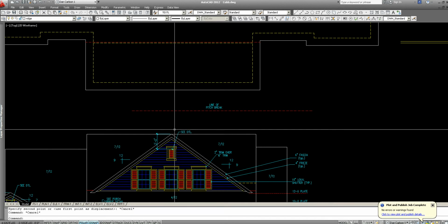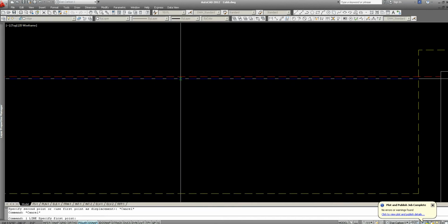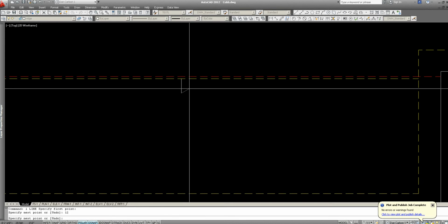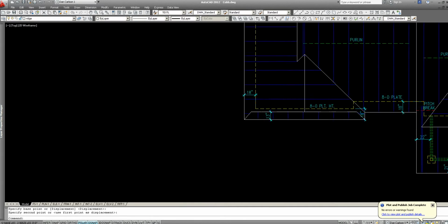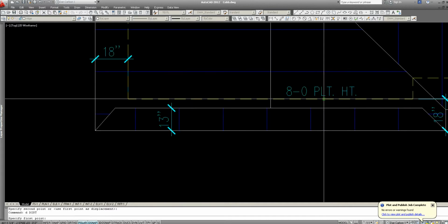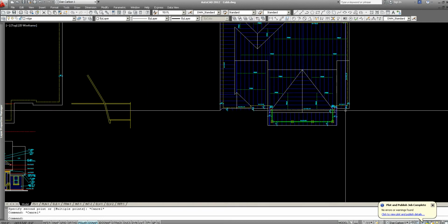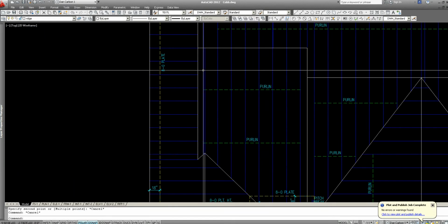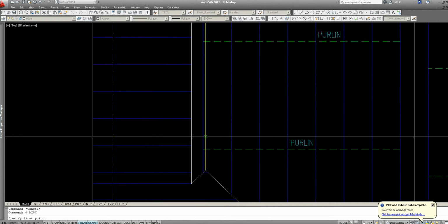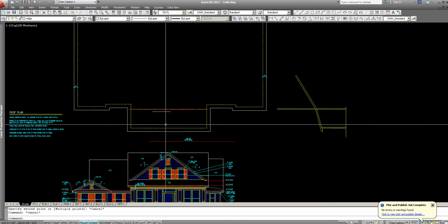So then we know that our gable end, let's do a 12-inch overhang because I think 12 inches is more appropriate for gable ends. In fact, if we look over here, we can see that this gable that they've given us here is only 5 inches, which is also too small. And this gable end over here on this side is 12 inches. And this gable end here, you can't see it, but it is also 12 inches. 12 inches is a more normal gable size.